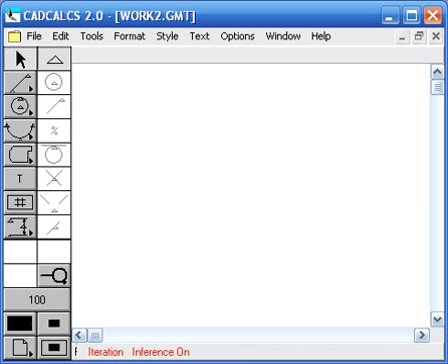In this lesson, we will look at the GoalSeek capabilities available both in CAD Calcs and GraphicCalc 2010. GoalSeek is essentially a way of back solving geometry to meet and satisfy a stipulated design goal, and the goal can be a value which has been measured or calculated.